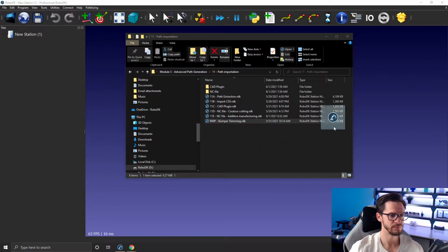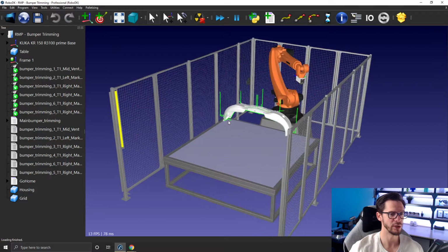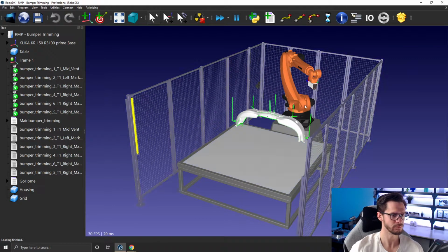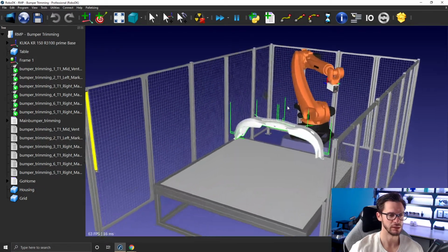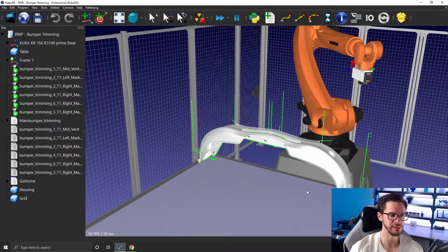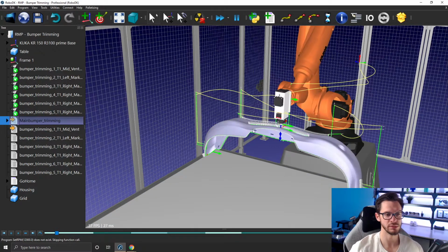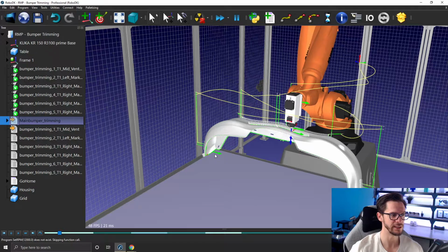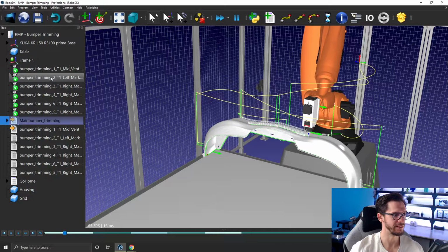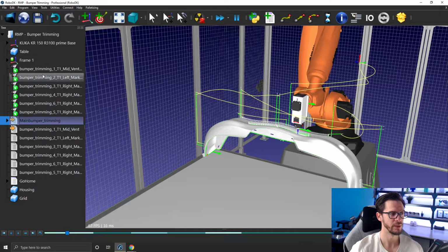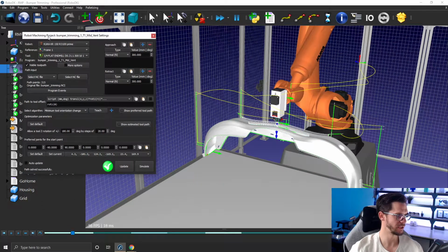Let's bring a small example here of what a robot machining project can look like if you are bringing in NC files, so milling, or in this case cutting files. If I start this program here, this was one G code, or one NC file. In fact, RoboDK, I'm going to show you why later, created out of that a bunch of smaller programs.